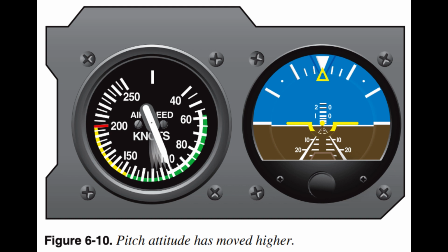Pitch attitude instrument crosscheck. The altimeter is an important instrument for indicating pitch attitude in level flight except when used in conditions of exceptionally strong vertical currents, such as thunderstorms. With proper power settings, any of the pitch attitude instruments can be used to hold reasonably level flight attitude. However, only the altimeter gives the exact altitude information. Regardless of which pitch attitude control instrument indicates a need for a pitch attitude adjustment, the attitude indicator, if available, should be used to make the adjustment.